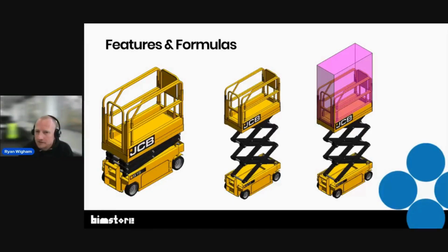A yes/no parameter in there, for example, you can see that pink box on the top. In a project, that's the safe working height of the basket, an instance parameter. So using visibility parameters and a yes/no formula and materials, a user can put that in, select the height it needs to go, and it shows that safe working height. So it can go into a model for putting on the maintenance access strategy drawings.